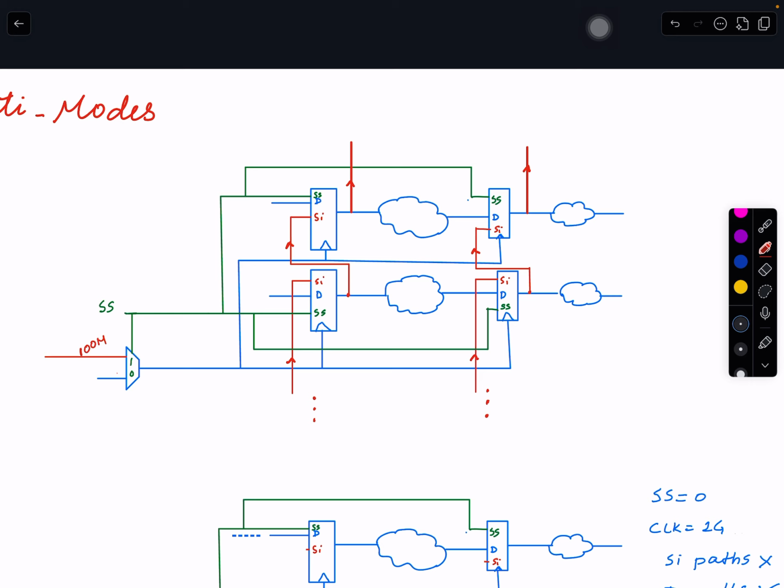And the other one is, let's say, a 1 gigahertz clock. It has its own PLL or source. Let's go back. Okay, so we have a clock here, we have a clock here. How many clocks is each clock pin of each flip-flop getting? 2, right? This clock and this one.